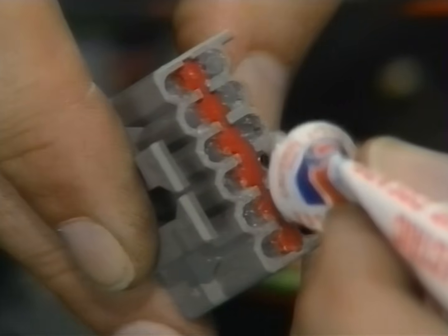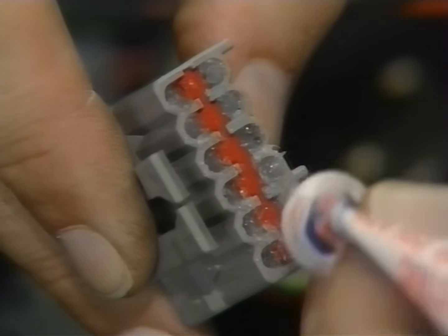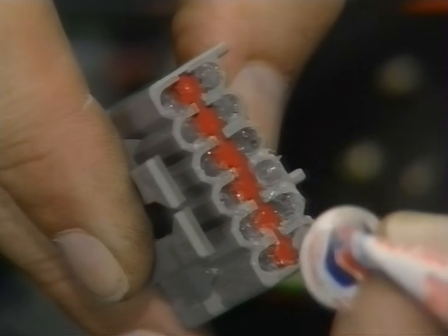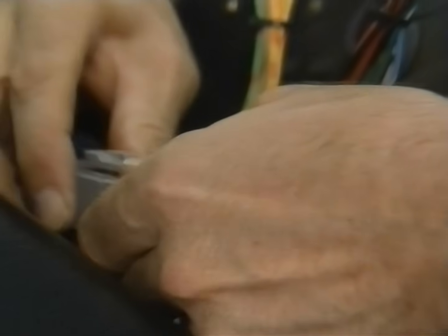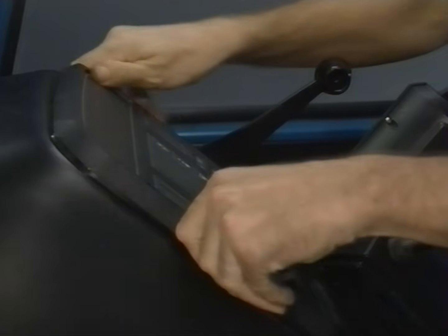To check the connector, clean the connector pins, apply dielectric grease to them, and reconnect connector A. If the EIP still doesn't function properly, install a replacement central display module in the instrument panel and check the operation.